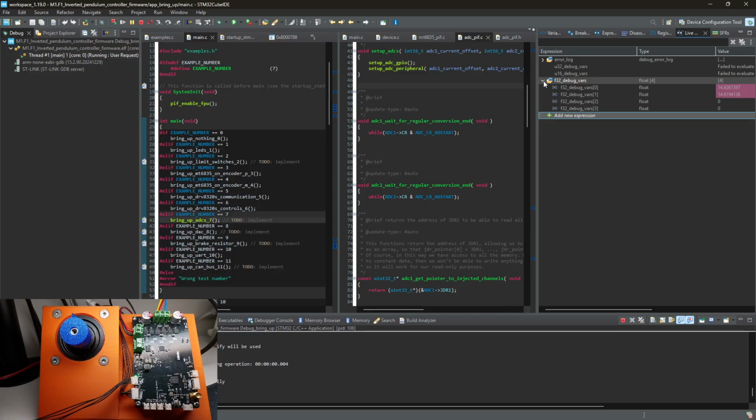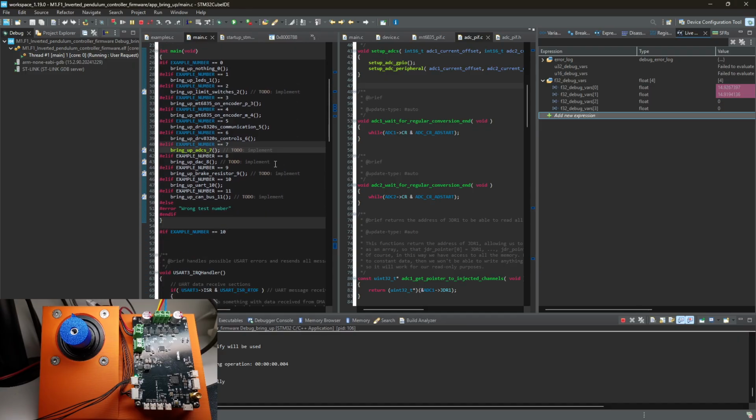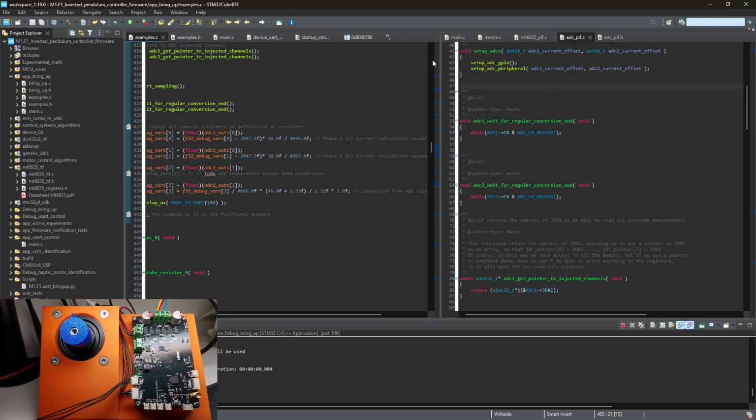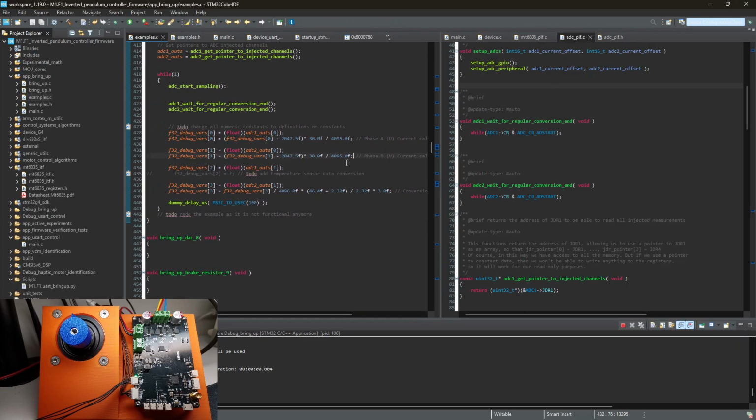Now let's see if our currents are as expected. This shows about 14, which is correct because the current measurement we are doing is middle point, because we would like to measure both positive and negative currents, and we can do it up to 15 amps, and 15 is a middle point I don't remove, I believe, so it shows an actual correct value. Yes, so let's actually subtract it so that we can show an actual value we measure. And this actual value we measure can be used for calibration.